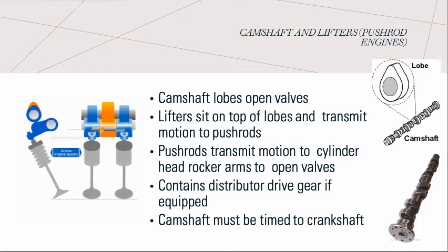movement of the crankshaft. During the four-stroke combustion cycle, which is intake, compression, power, and exhaust, the crankshaft turns twice, moving each piston up and down twice, while the camshaft turns once. This results in each valve opening one time for every two crankshaft revolutions in relation to the piston. This way, only the intake valve will open on the intake stroke, both valves remain closed during the compression and combustion strokes, and only the exhaust valve opens during the exhaust stroke.